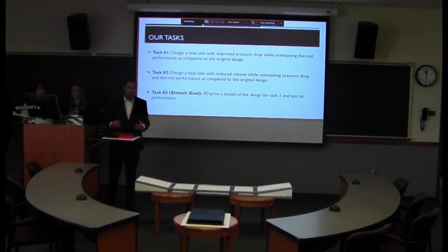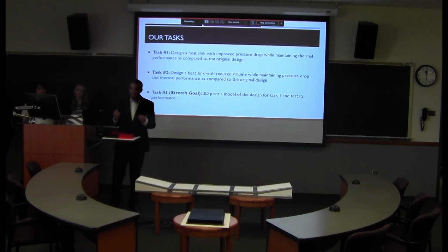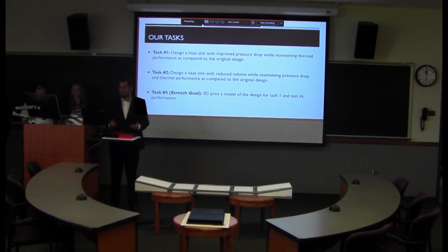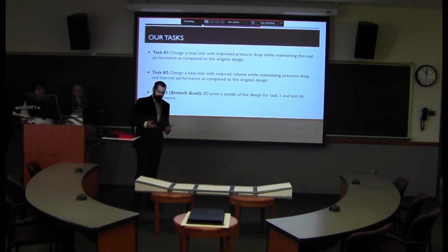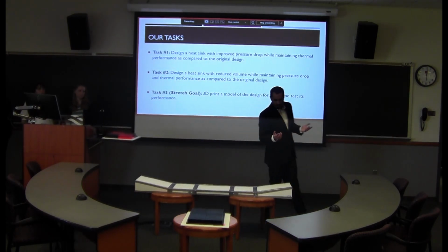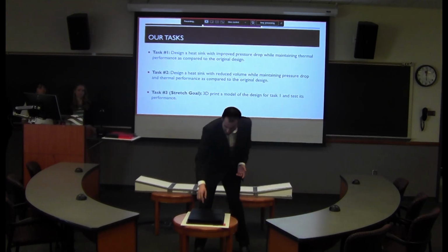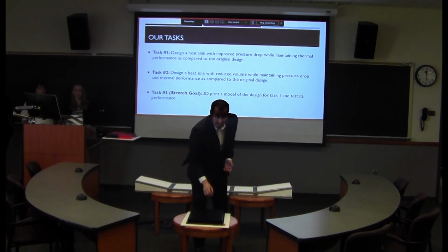So BPMI's main goal for us was to redesign a heat sink using complex geometries made possible by additive manufacturing and validating our results using a computational fluid dynamics program. The first task was to design a heat sink with an improved pressure drop while maintaining the same thermal performance as the original design. For those who don't know, a pressure drop is the difference in pressure between 2 points of a fluid system. So in our case, pressure we measured from the front of the heat sink, where the fluid enters the device, and the back of the heat sink, where the fluid leaves the device.